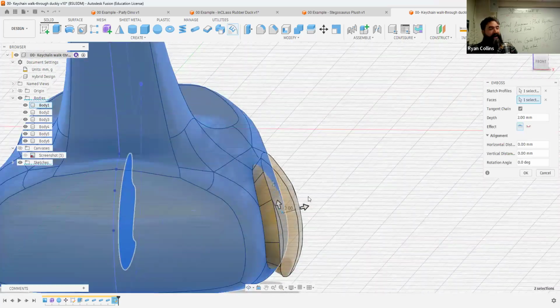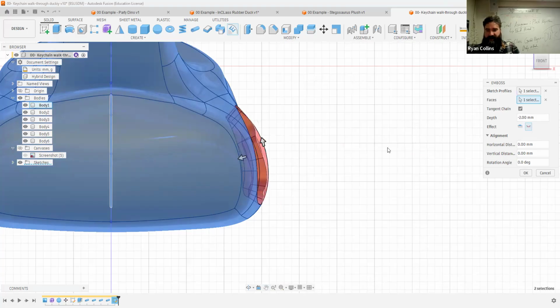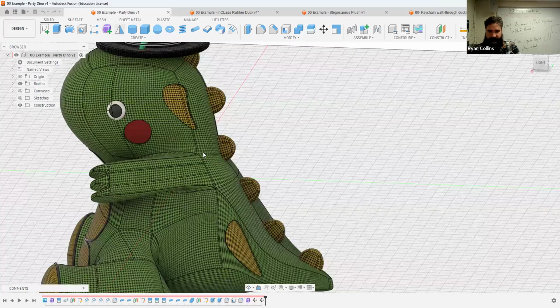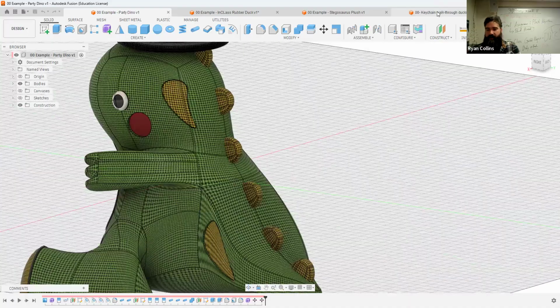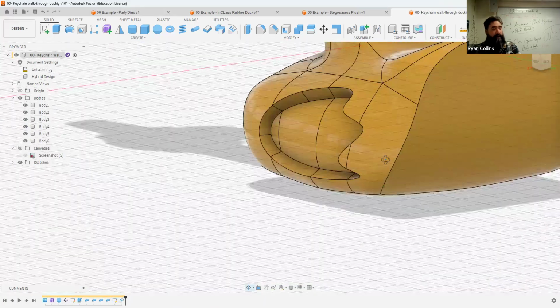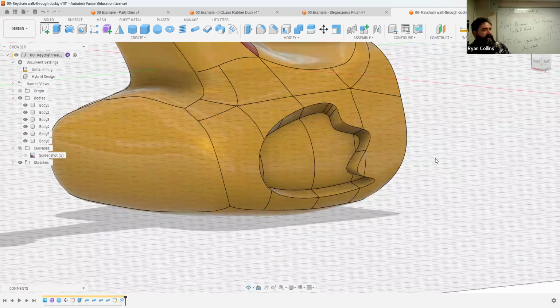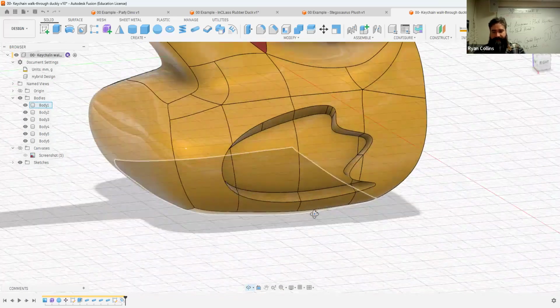But don't forget, emboss is not a straight extrude. It's essentially offset face. So you're going to get that odd curvature, so don't go too far with it. Or you could deboss, which just cuts inward. That's how I made the little indentations on the side of the dyno body there. So deboss would drop it downward. Both are functional, but it maintains the curvature of the object, shrinks it, pushes it in or out. You can repeat that for the other side, and that would work great.